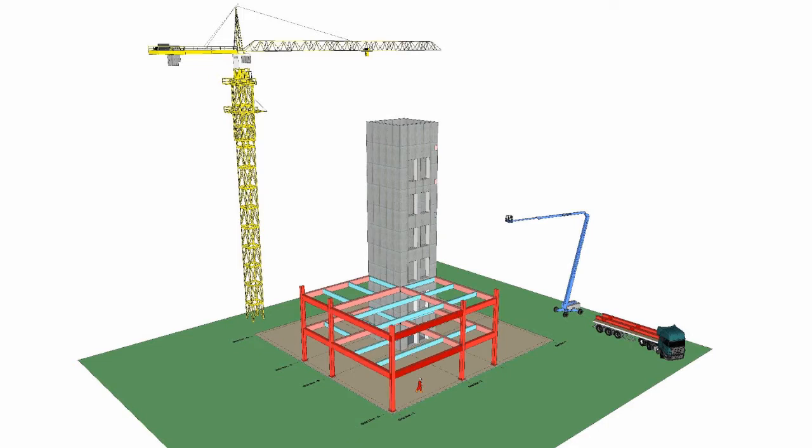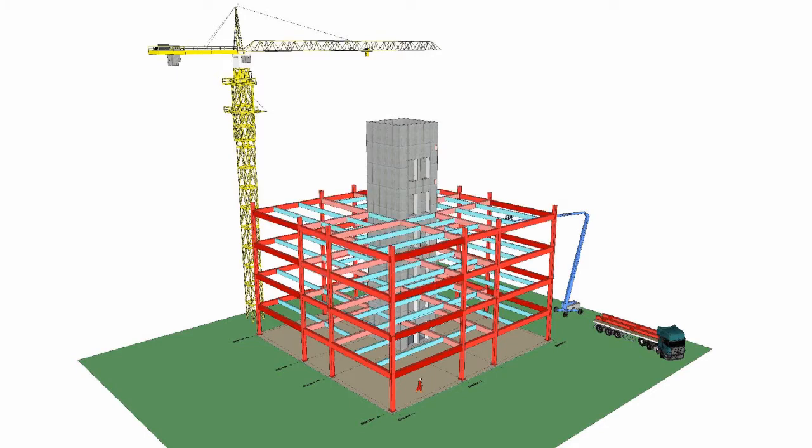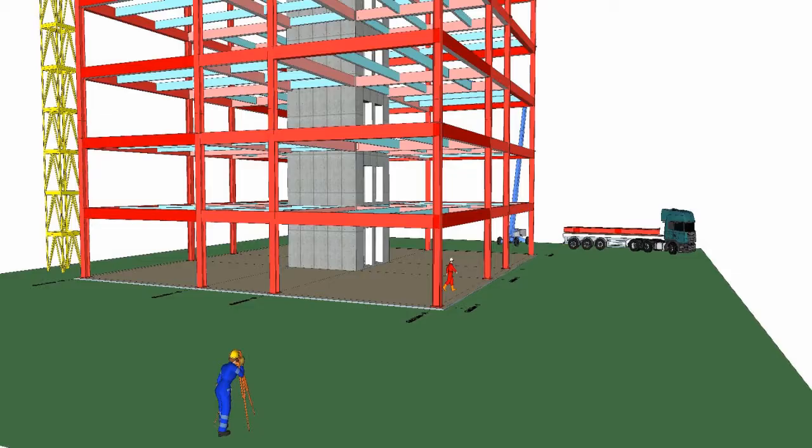The outline erection methods. Use the reinforced concrete stairs and lift core to provide stability to the partly erected steelwork. Install any required temporary bracing or propping to the incomplete structure.